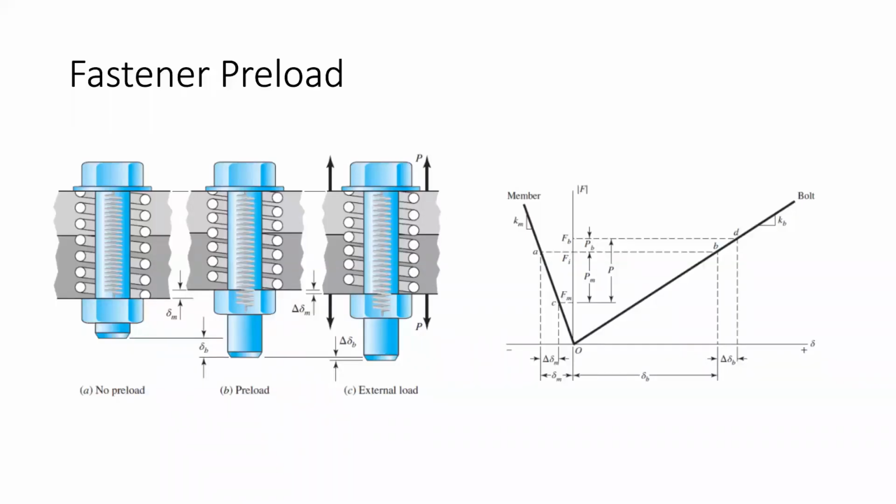Okay, so I couldn't really find an image in the textbook for this, but another really important aspect of fastener design is basically how to size your fasteners and how much to preload them, right? So in general, most of the time you want to preload a fastener as much as you can, and you can have one of two ways that the system can fail. Either the fastener that you use has threads that are weaker, so the fastener threads literally pull apart, or the mating material, what you're threading into, in this case that would be the nut, has a weaker material, so that fails first. More often than not, it's always going to be the material. Your fastener is usually made of a relatively hard and high yield steel, whereas your material might be something like aluminum or a softer steel. So the lower of those two strengths is basically the most that you can preload the system, right?